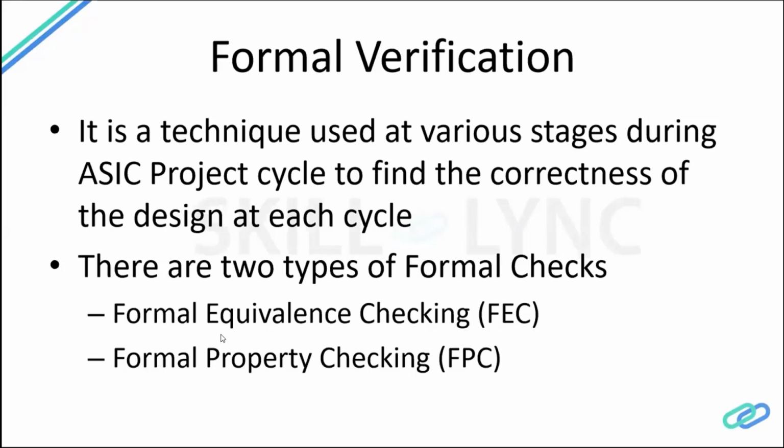Similarly, we do this formal equivalence check or formal verification at each stage. RTL versus synthesized netlist, we do. RTL versus layout netlist, we do. So at each stage, wherever we have a proper netlist, we compare that with the previous stage netlist so that we can check whether both are right or wrong.